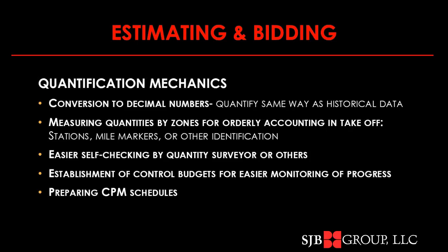And you're doing this takeoff at the time of your estimate so that on the successful project, you can use these quantities to establish control budgets for the easier monitoring of your construction progress. And these quantities may also prove helpful as you're pulling together a CPM schedule, which is very detailed.